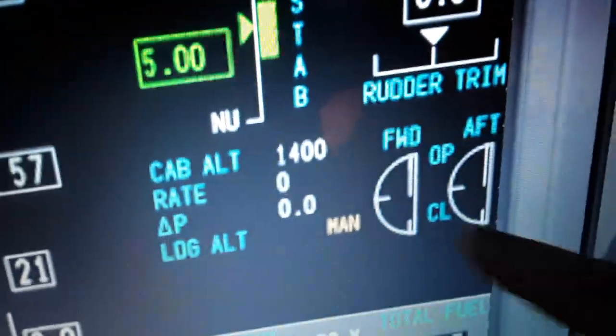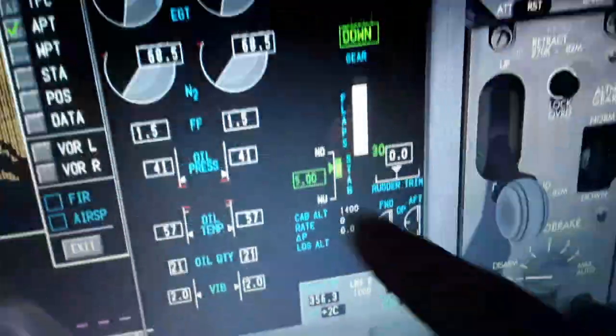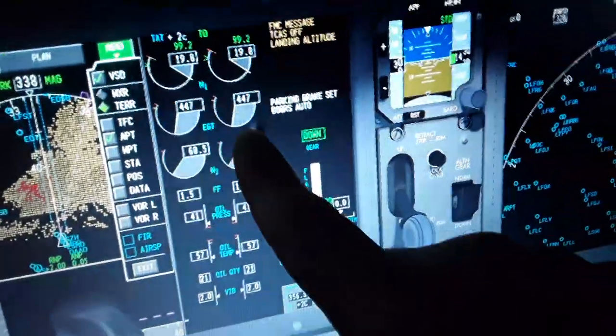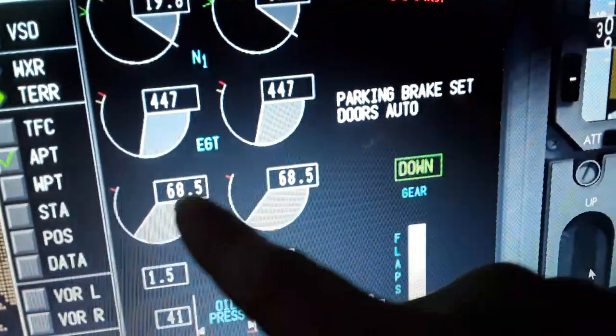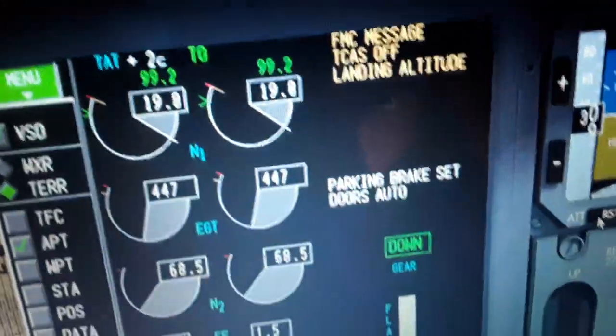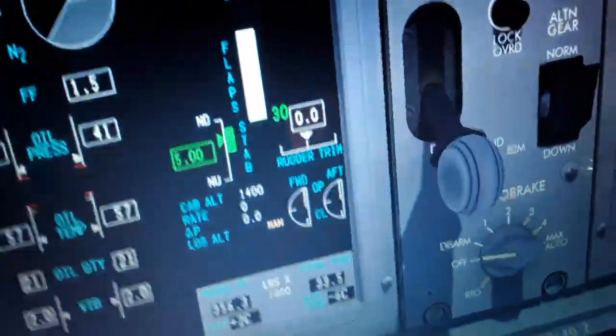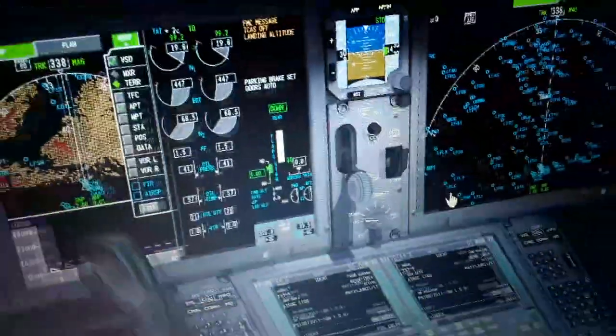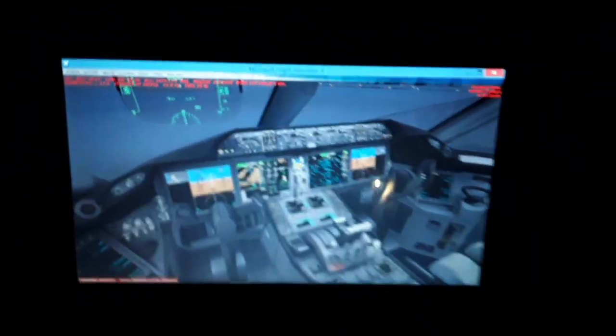In most aircraft, they receive pressurized air from the 5th and the 9th stage of the engines over here. The high pressure compressor turbine, we have the 5th and 9th stage. Also we have the front fans, the bleed air, so it supplies the cabin pressurization, and the wing anti-icing over here.